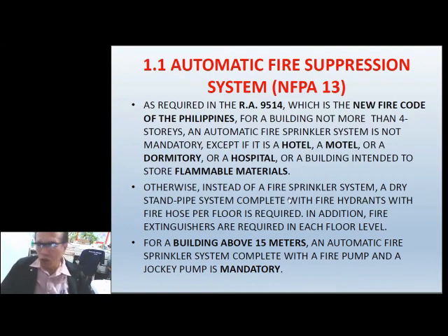So these are loads. Otherwise, if it is not governed by these requirements, hotel, motel, dormitory, hospital, or there are no flammable materials, then usually what you provide are equipment that do not need electricity. I mean, no need to power up, no motor, no fire pump, no jockey pump.